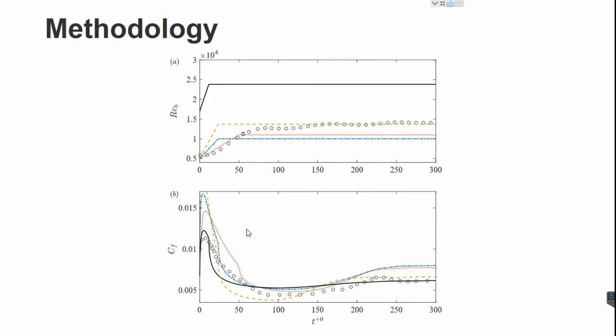And these are some of the results of the direct numerical simulations. So here in this plot, we can see that we're changing the bulk Reynolds number from an initially turbulent Reynolds number. Before time 0, we had constant velocity for a very long time. Then at time equals 0, we ramp up the flow, so we accelerate the flow rate.